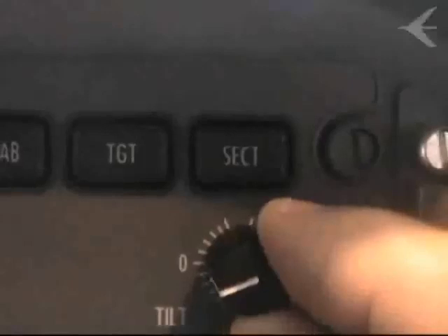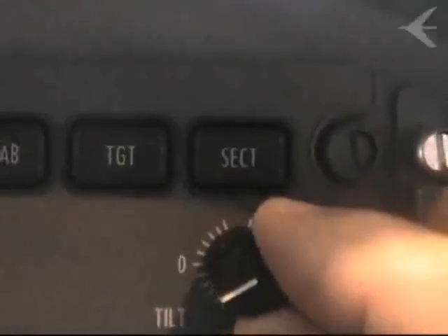Climb, cruise. For overland operations, adjust tilt until ground targets appear at the display periphery. Storm cells displayed between half scale and the outer edge of the display should be monitored, tilting the antenna periodically up and down and alternating range setting as necessary to see the total weather and the flight path. If altitude changes or a different range is selected, adjust the tilt control as required to minimize ground returns.